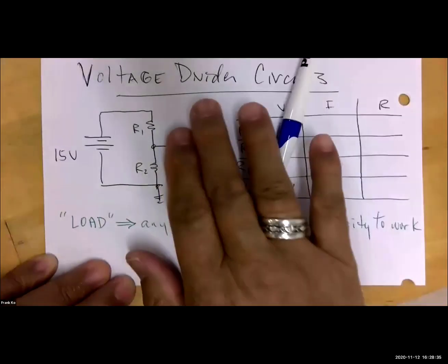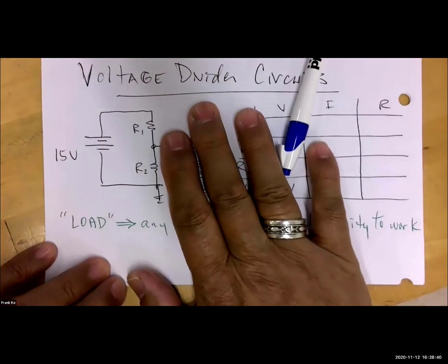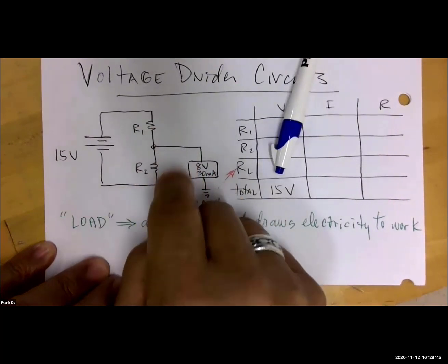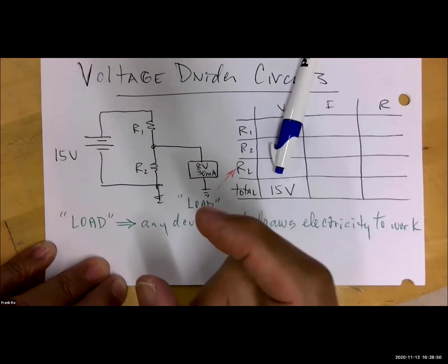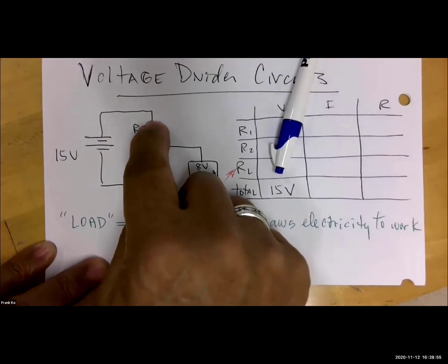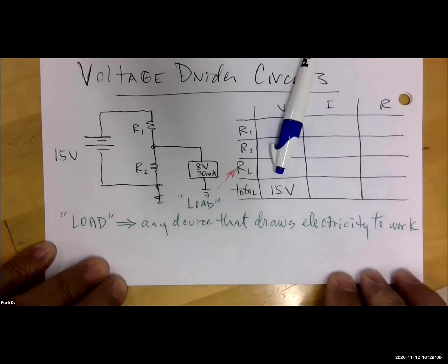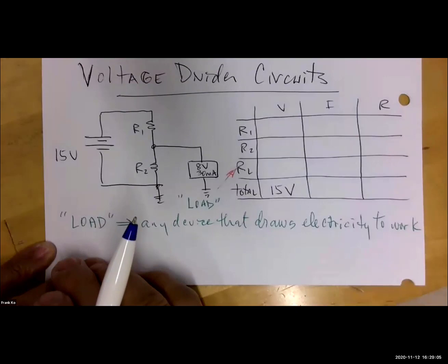They look like they can be. If I remove the load, then clearly R1 and R2 are in series. But because I have a load coming out here, I have a split of current. So series means that R1, R2 would have the same current, but I clearly don't have the same current going through R1 and R2 because there's a split here. So perhaps you want to rephrase what you want to fill in the chart. Yusuf? I don't know really.